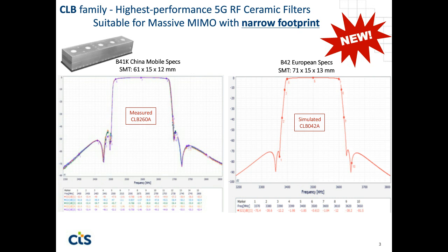So you need a combination of a relatively small size, and in particular, this part has been optimized for a narrow footprint. So the part's a little thicker, but allows you to finely pitch the parts for neighboring MIMO transmit paths side by side in a tight pitch as might be needed in a massive MIMO system.